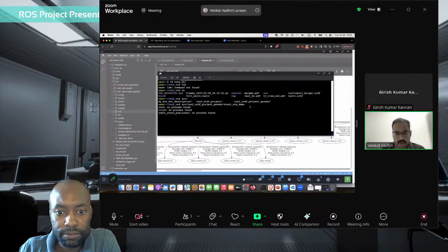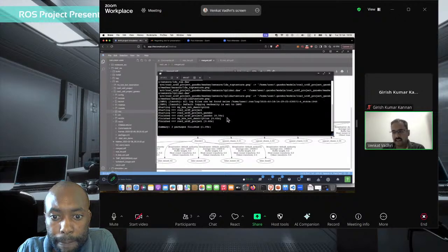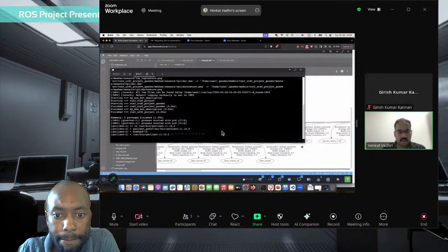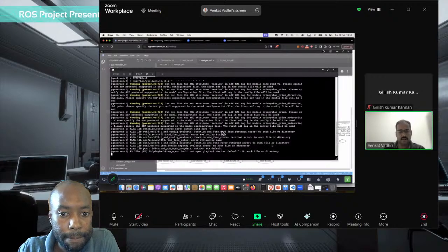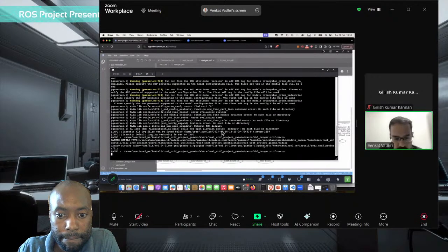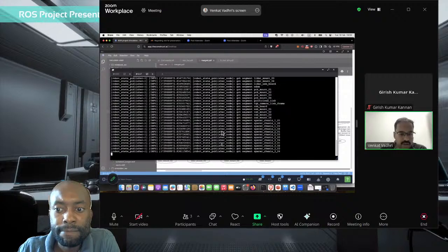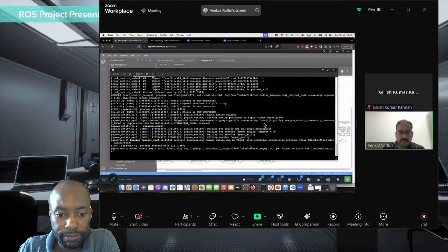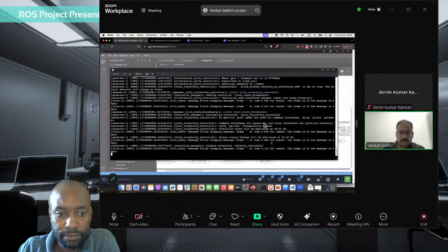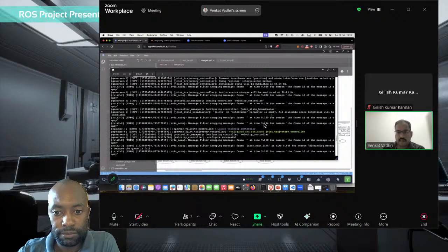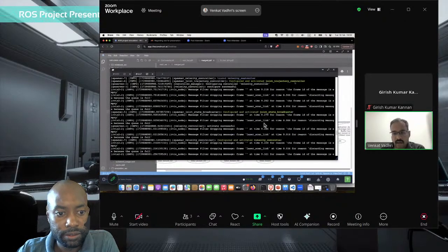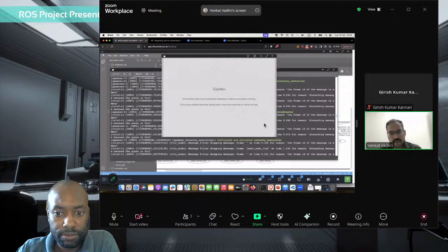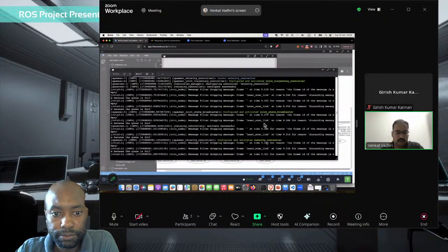There are too many commands, so I bundled them into a file. Let's see what it looks like in the simulator. It should launch 3 things: an RViz, a Gazebo simulator instance, and the launch version. If you see the green ones, it means that the Gazebo plugins have loaded and it is able to broadcast properly. Usually this has a starting problem. We need to do this again.